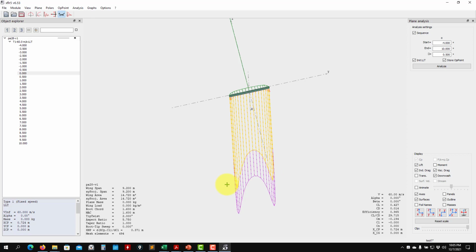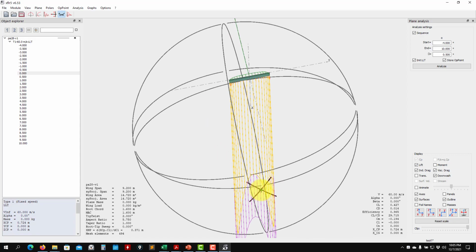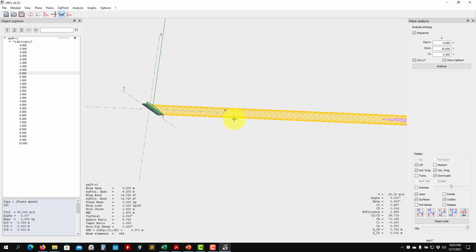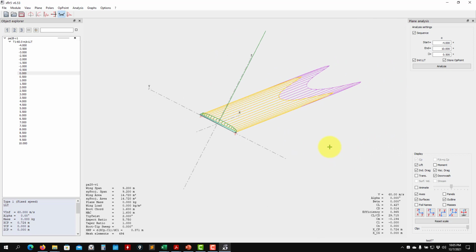Okay, but however, as a designer, we can directly act on the induced drag. We can reduce it. Instead, the viscous drag is very difficult. It's related to the surface. So the only thing that we can do there is choosing a natural laminar flow airfoil, and designing a very clean wing with no interference, nothing to reduce that one. But that is difficult to control. Instead, the induced drag can be controlled, okay, by using good design practices that we address in the review.